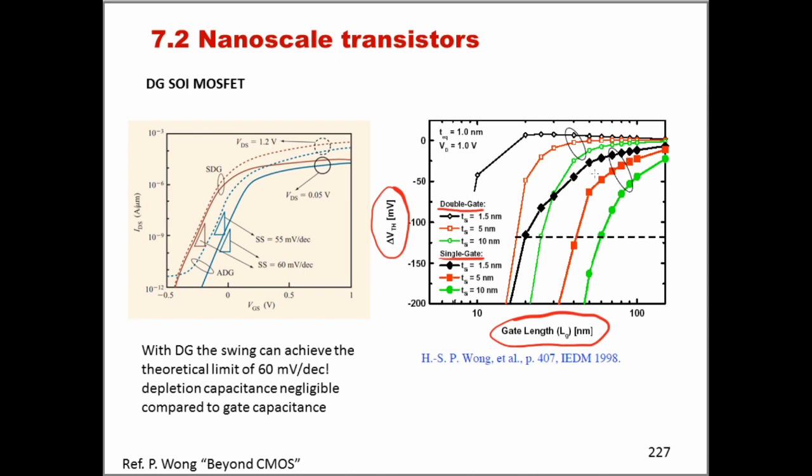If we compare, for example, the black curve with full symbols and empty symbols, we can clearly see that in the case of the curve with empty symbols, the deterioration of the threshold voltage starts when the device is already very, very small. You can see that the deterioration starts here when the threshold voltage starts dropping, at 20 nanometers, while for the black curve in full symbols, the deterioration had already started probably somewhere here at 100 nanometers.